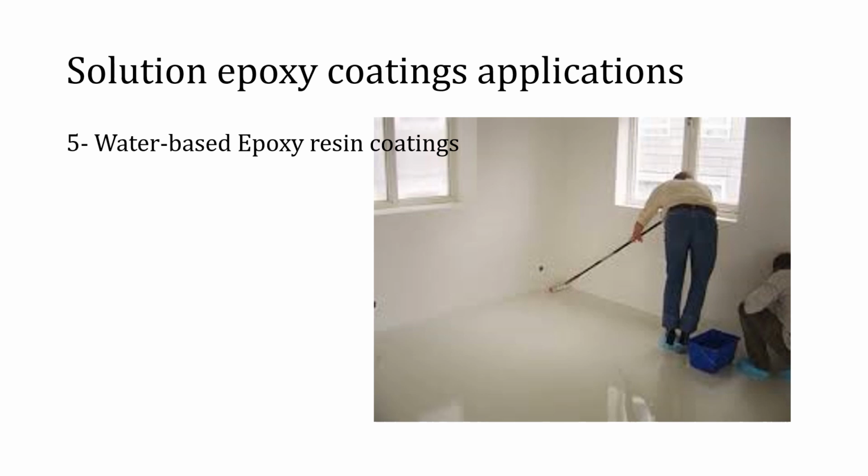Water-based epoxy resin coatings can also be formulated for both anodic and, less commonly, cathodic electrodeposition for appliances and automotive industries. Compared with spraying applications, in electrodeposition application, it is possible to obtain more uniform coatings, and also the wastage of the coating is minimal as the loss due to the overspray is eliminated.